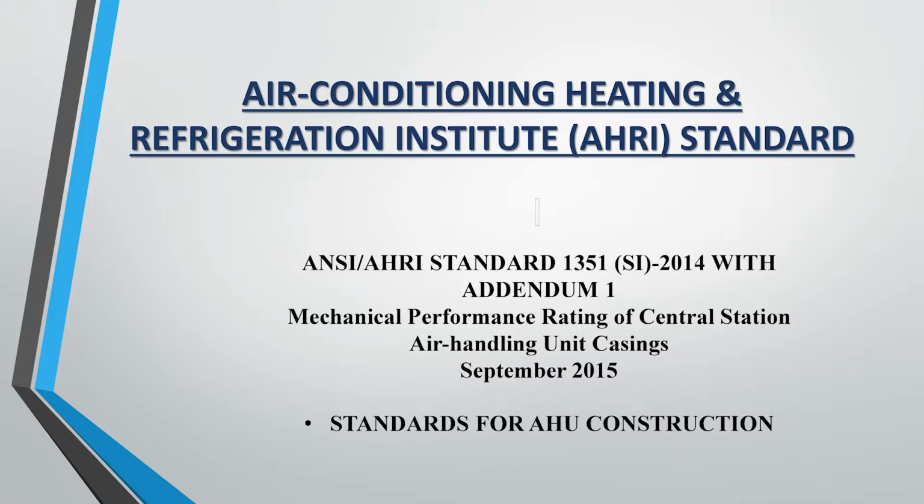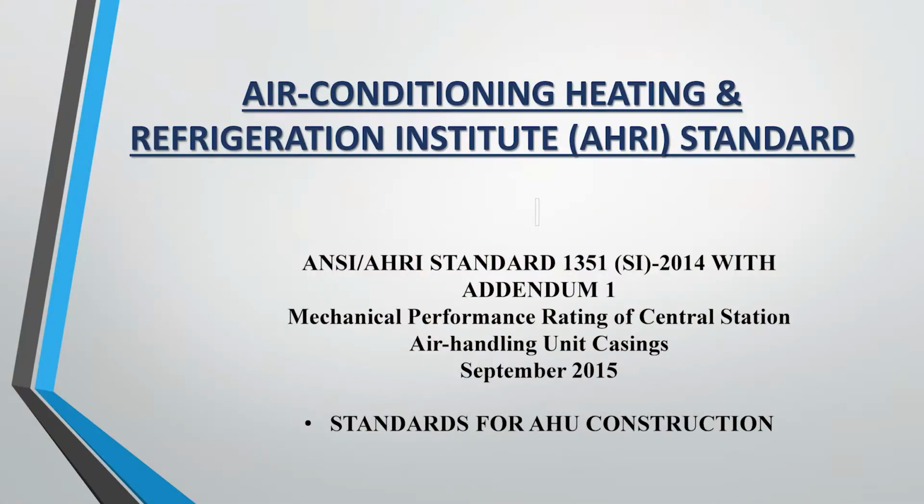This is the SMACNA leakage classes. That top line there, I think you all can see that. We have seal class C, B, and A. Of course, transverse joints, seams, and then A is absolutely everything. So A is basically what you want to shoot for when you're on any job, in my opinion. If you start shooting for other things, it just leads you down a path of terrible results. And it's not that difficult. And then you have at the bottom leakage class based on rectangular and round metal.